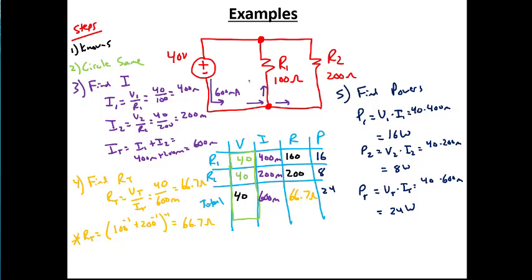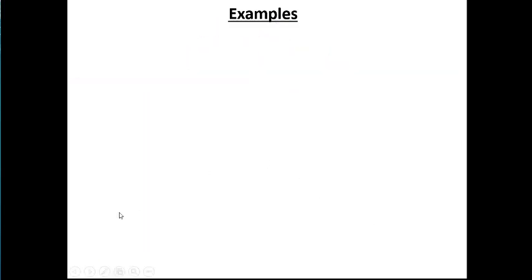So we get 400 milliamps here, and we get 200 milliamps here. And then that 400 milliamps goes through the resistor, and it's still 400 milliamps. This current, this 200 milliamps, goes around the corner, goes through this resistor, goes around this corner, and it stays 200 milliamps. Then the 400 and the 200 get combined back together, and we get 600 milliamps. And so this is the path of the current flow. All right, let's go to the next problem here.